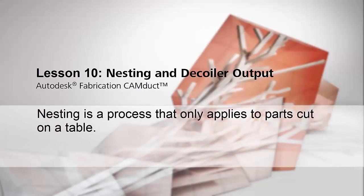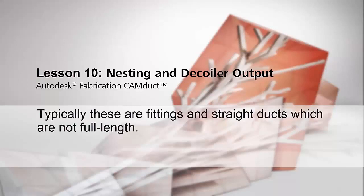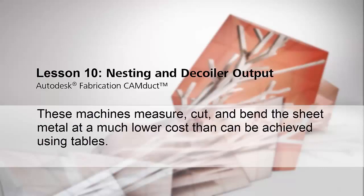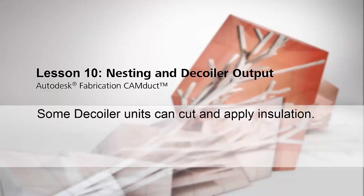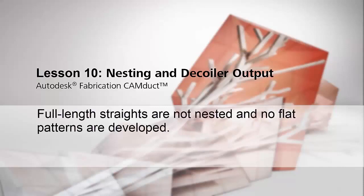Nesting is a process that only applies to parts cut on a table. Typically, these are fittings and straight ducts, which are not full length. Full-length straights can be fabricated on decoiler units. These machines measure, cut, and bend the sheet metal at a much lower cost than can be achieved using tables. Some decoiler units can cut and apply insulation. Full-length straights are not nested and no flat patterns are developed.